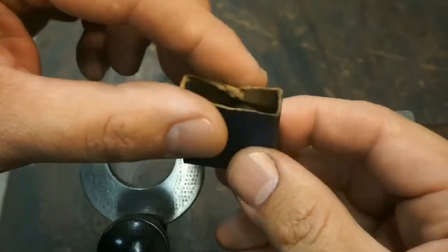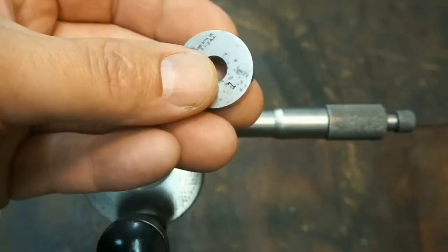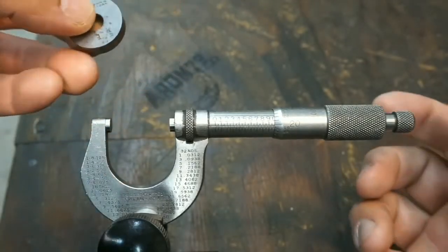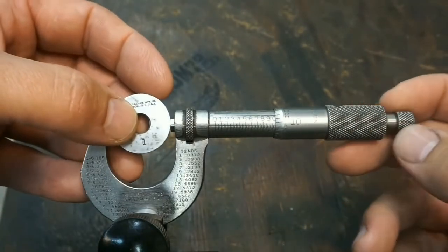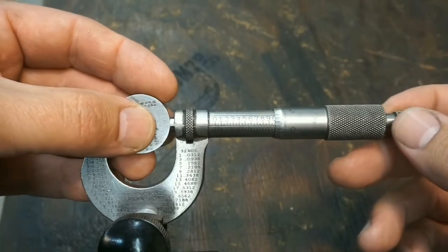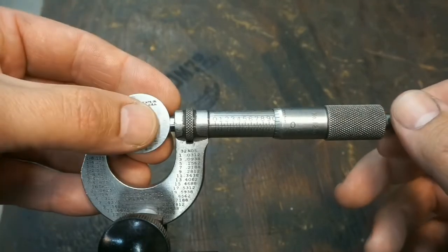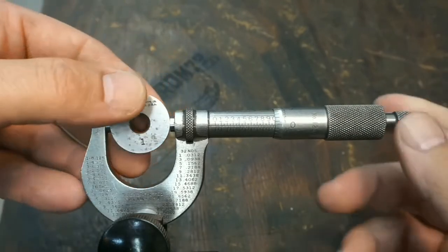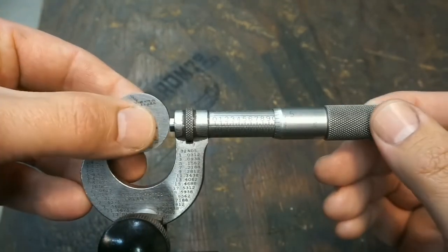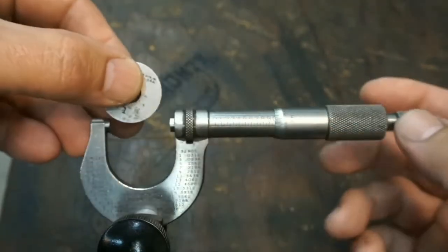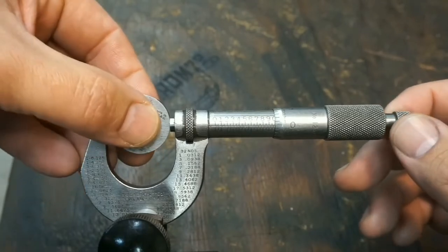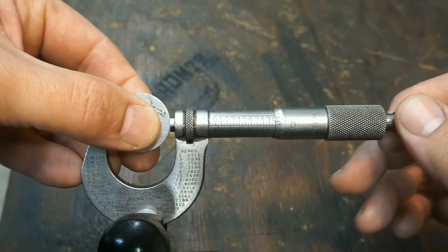This was my granddad's here, and we'll use this to check the mic that we're using there and make sure that we're on. This is another good thing to show you for the guys that are learning this stuff. So I'm going to put this in there, and I'm holding this mic in a clamp here to try to help with the video. So this isn't normally how I measure things, but just trying to bring you some good video there. So we're going to put the gauge in between the anvils there and get it centered up, and I'm just using a ratchet thimble, and I can feel it that it's in there properly.